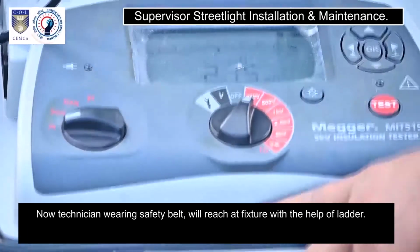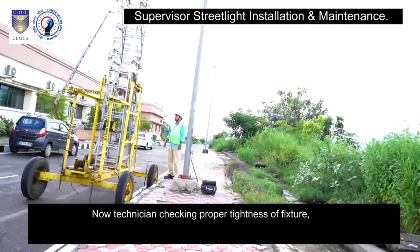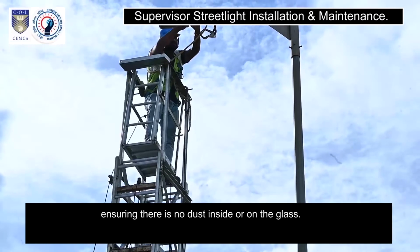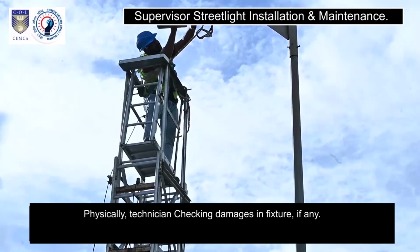Now the technician, wearing a safety belt, will reach the fixture with the help of a ladder. Now the technician is checking proper tightness of the fixture, ensuring there is no dust inside or on the glass. Physically, the technician is checking for damage in the fixture, if any.